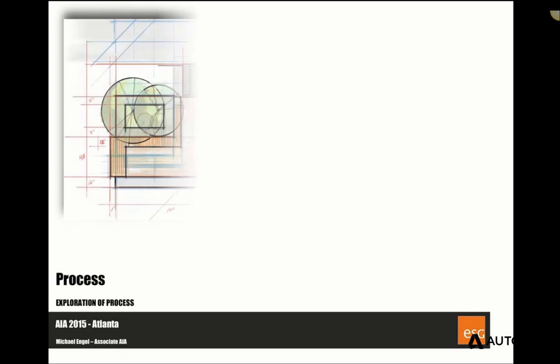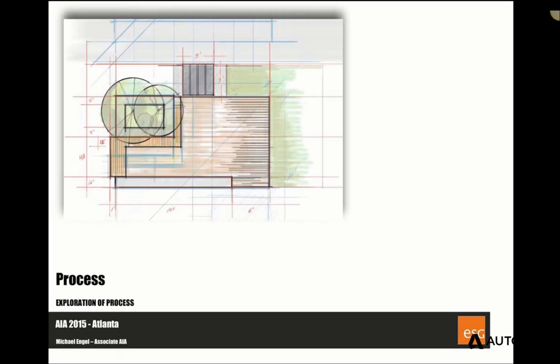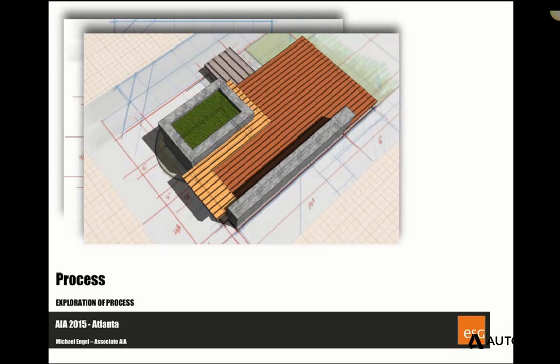So this is maybe a summary of what I just described, a little more formal. A lot of times I'm working in Sketchbook Pro, creating an idea very quickly, very traditionally, but in a digital format. Bringing that right into FormIt, extruding off of it, creating the mass, doing the rotation, and materials setting too.